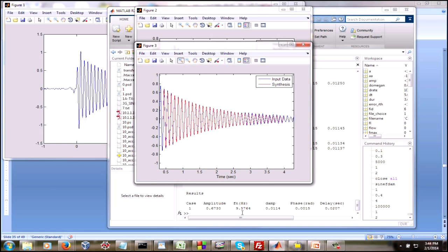But then after it's launched, we have to figure out every 5 seconds or so what the natural frequency is going to be, because that's going to be changing in flight. It's going to be increasing in flight as mass is expelled. In other words, the fuel mass from the rocket propulsion system is converted into exhaust gas and expelled. So those are some of the things we need to look out for,